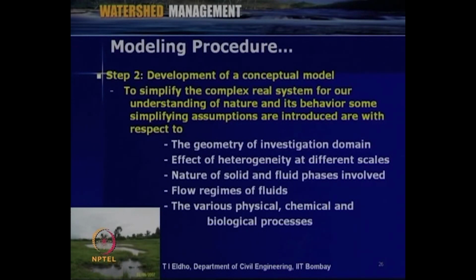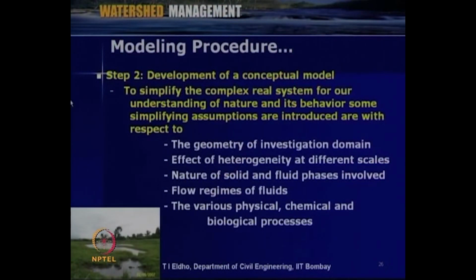We have to put in a lot of intuition and a lot of assumptions, and then come up with a conceptual model that may truly, to a certain level, represent the real nature of the problem. What we are doing in developing a conceptual model is simplifying a complex real system for our understanding of nature and its behavior. We put in some simplifying assumptions with respect to the geometry of the investigation domain. Say, for example, a 3-dimensional problem we assume as 2 dimensions, or 2 dimensions to 1 dimension, or the effect of heterogeneity at different scales.